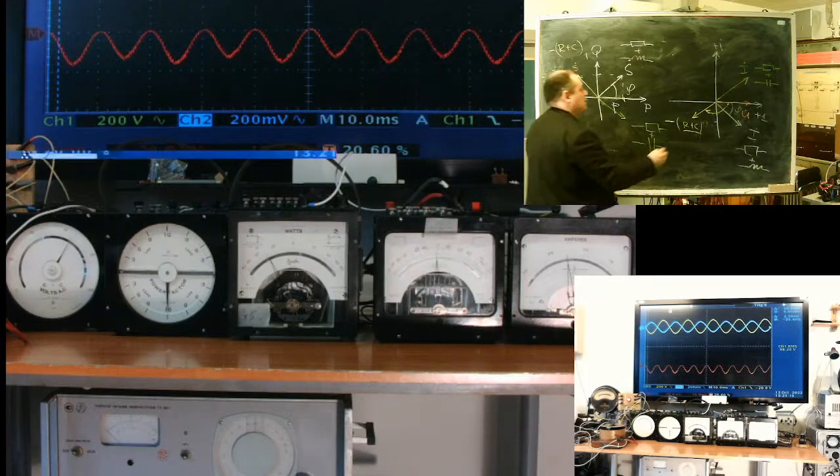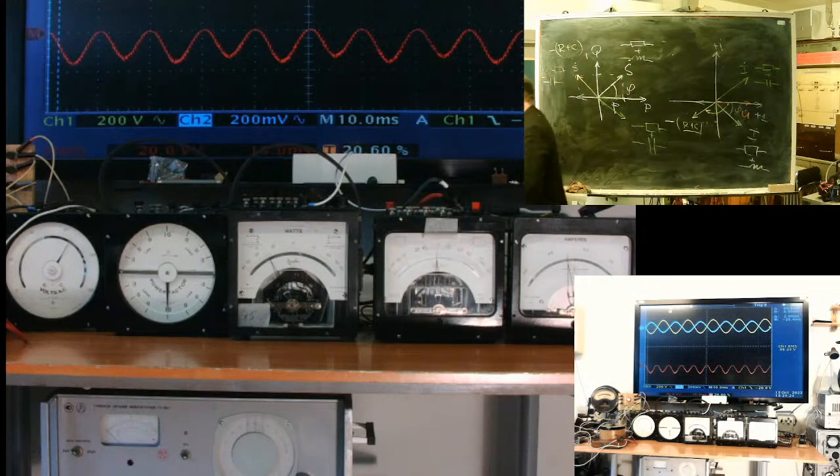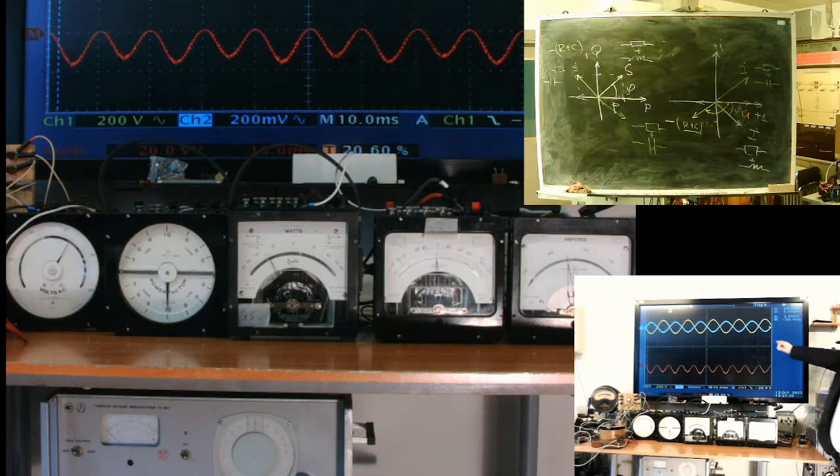It is here, generator, 180 degrees angular shift, and you can see zero reactive power, but active power is with a minus sign, negative. Meaning we do not consume power, we send active power to the grid, and we have a zero reactive power balance.